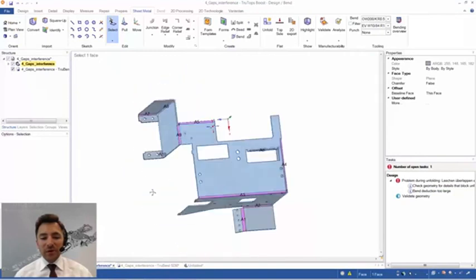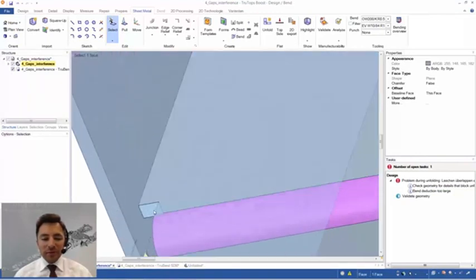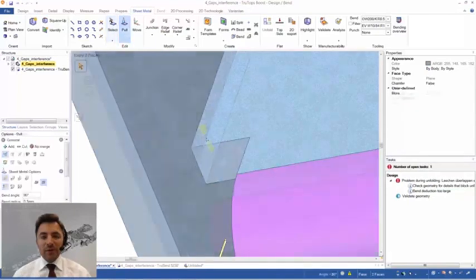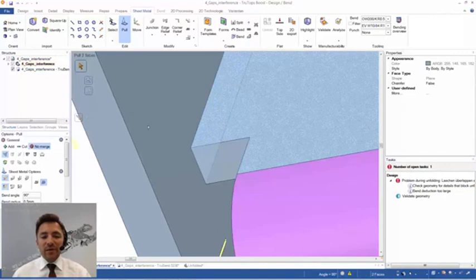We need to find, of course, that triangle, and that would be that area. And well, I just hover over to that face surface. I just press Control, turn my mouse wheel, and can basically select the face behind any other face.